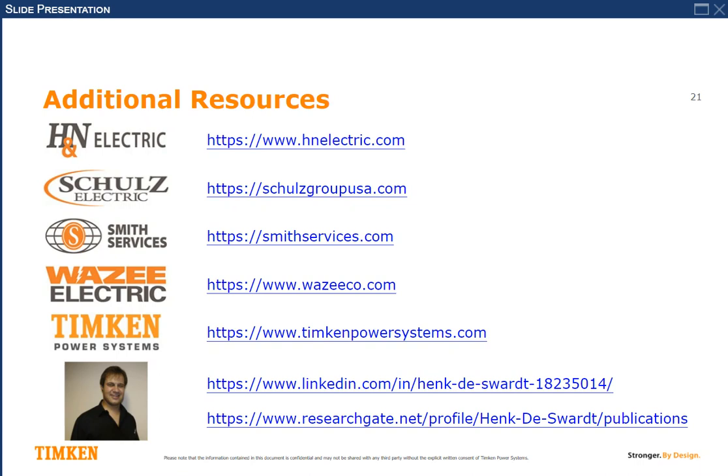The other thing that people do, those are the easiest, the temperature and the vibration, to monitor vibration. What people sometimes do is they do partial discharge measurements. That is really just done on 10 megawatt and larger machines, because the cost of that is really expensive. And there you are looking at machines that last 20, 30, 40 years, because partial discharge failures typically are a 20, 30, 40-year event. And you want to monitor that over time in order to prevent the failure.